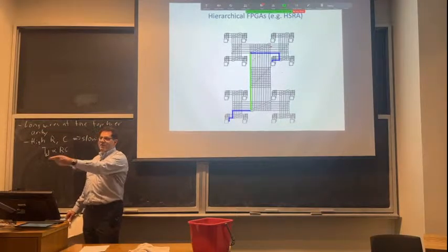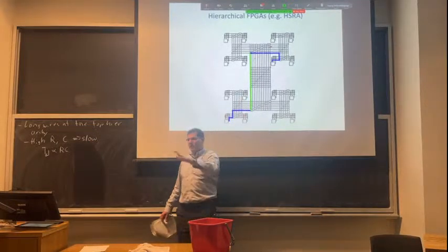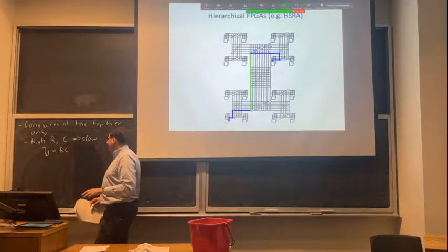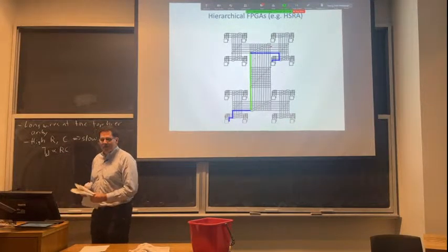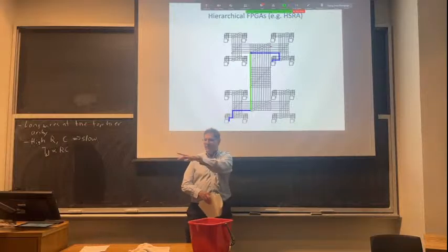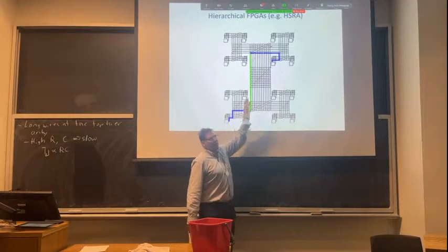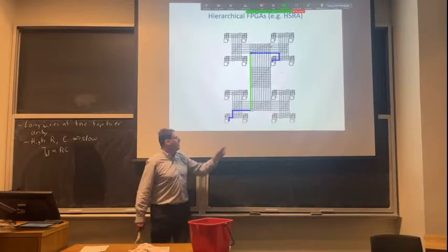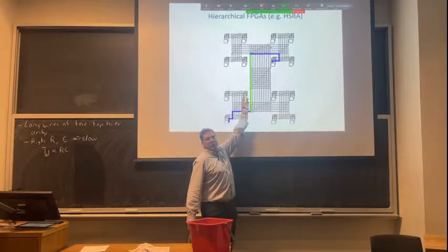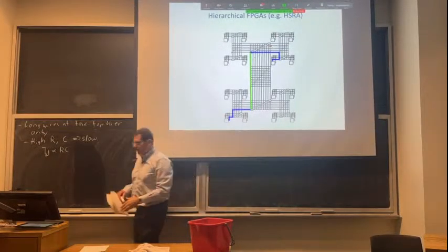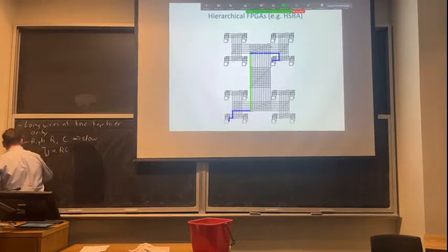So that's even better. Okay, so you're saying segment this into a bunch of pieces, put programmable switches in so we can break it up. So it's a good idea. I'm going to go only half that way first. So let's say we're going to go the rest of the way in the next section, so you're 2 steps ahead. If I want to go this far, I can rebuffer it. Okay, so to stop the resistance and capacitance from kind of growing too big, I can put inverters in here every once in a while, and that's what you would do. It'll cost me a bit of area, so we're going to need to rebuffer.